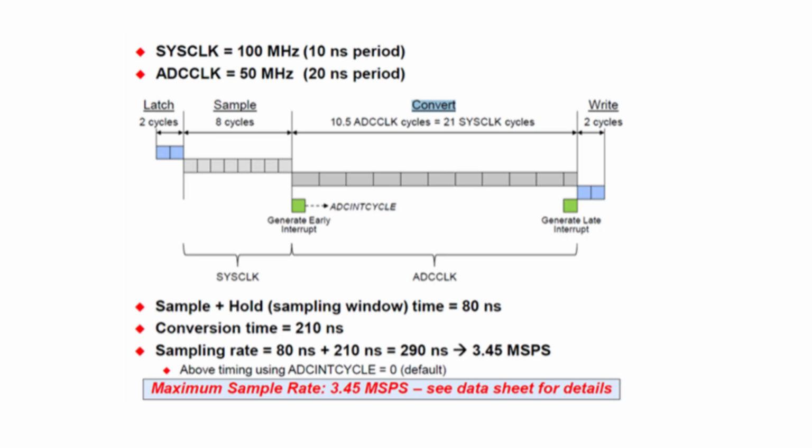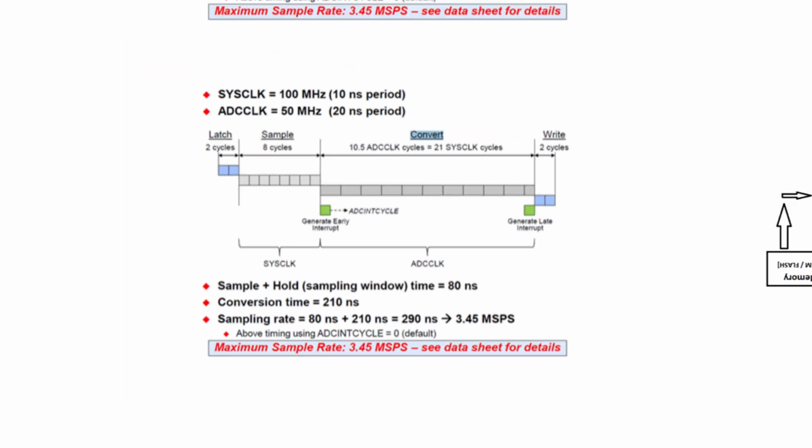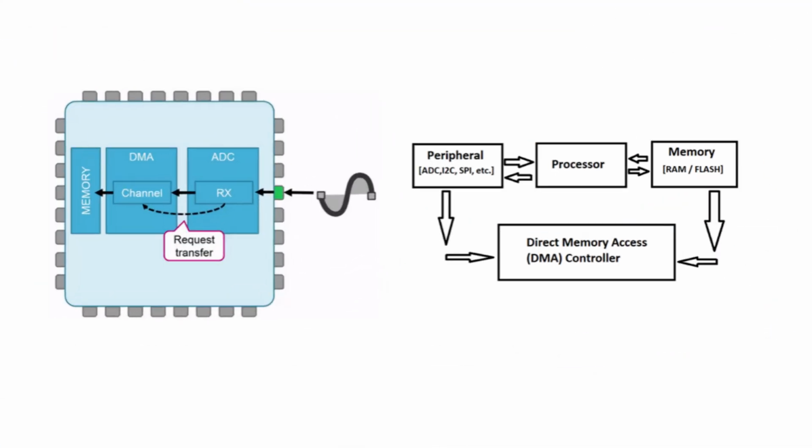So the buffer solves the impedance problem. Exactly. It lets you use a short sampling time for speed while still getting accurate readings from your high impedance sensor. Best of both worlds, at the cost of an extra component. Okay, this tuning makes sense. Now let's talk about the efficiency elephant in the room. DMA. You said it was a game changer.